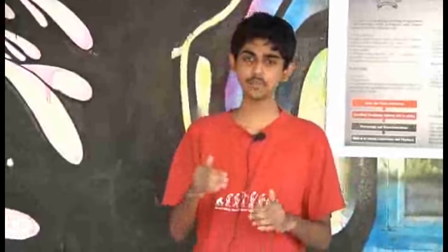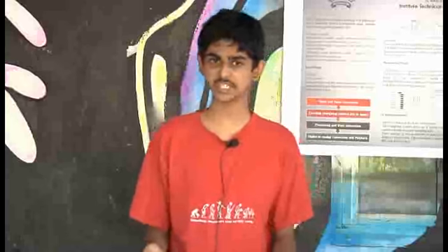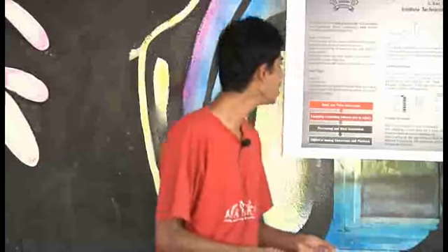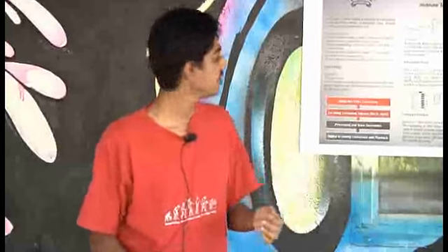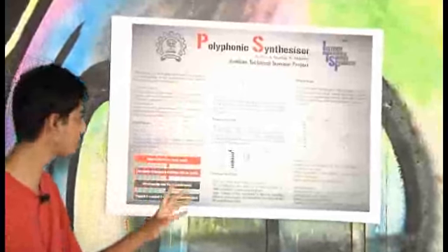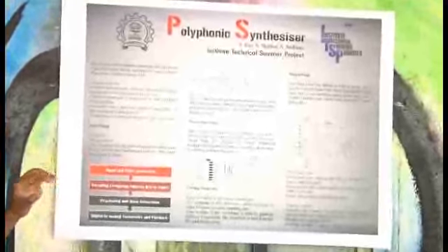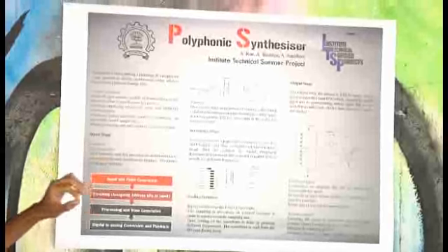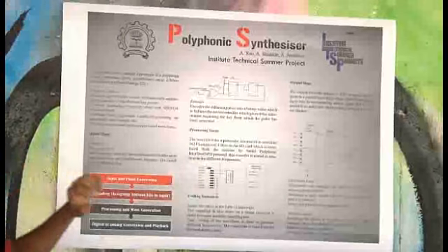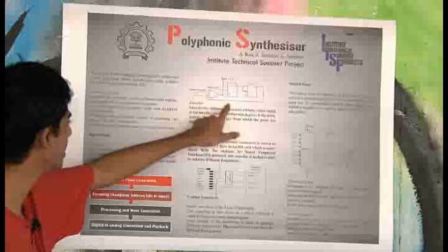Now the problem with encoding is that we will not be able to represent combinations of keys in 5 bits. For example, for 20 keys, the number of combinations of 2 keys is 20C2, which is well beyond the capacity of 5 bits to represent. So we have developed a system that, along with encoding, allows us to generate an input of multiple key presses. A key component of this design is this circuit over here.